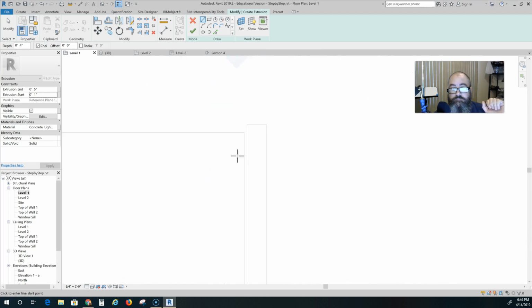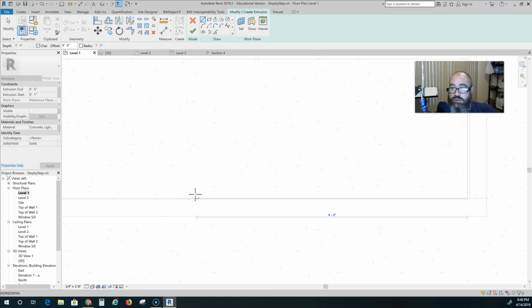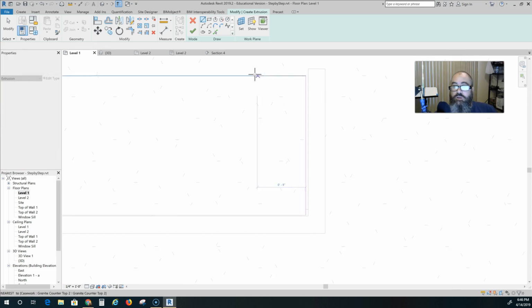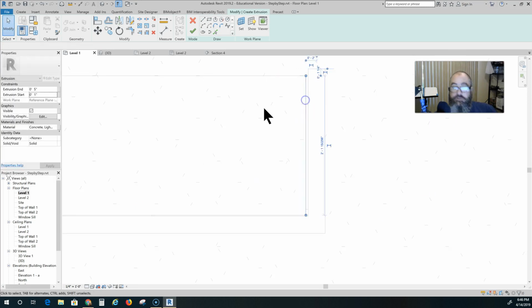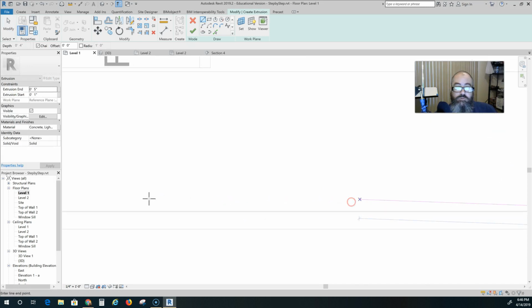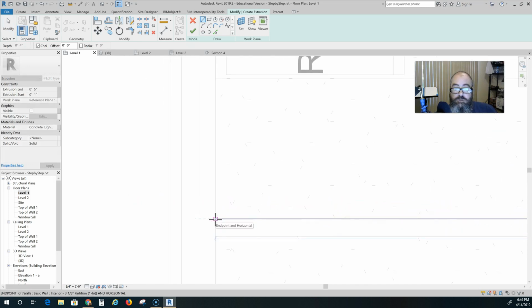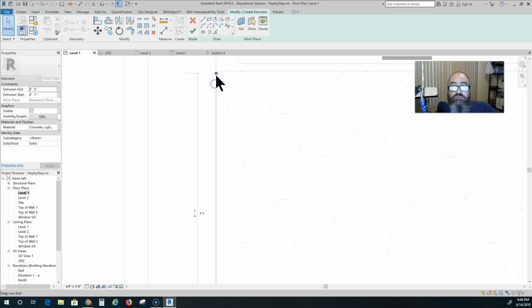Okay, so the extrusion would cover basically every bit of the countertop to where it would go up and mesh with the wall. And I should have done that a little differently. Let's do it this way. Start on the wall, come out, come around, all right, and what you can do is fix that. I should come a little further. You can do an offset.